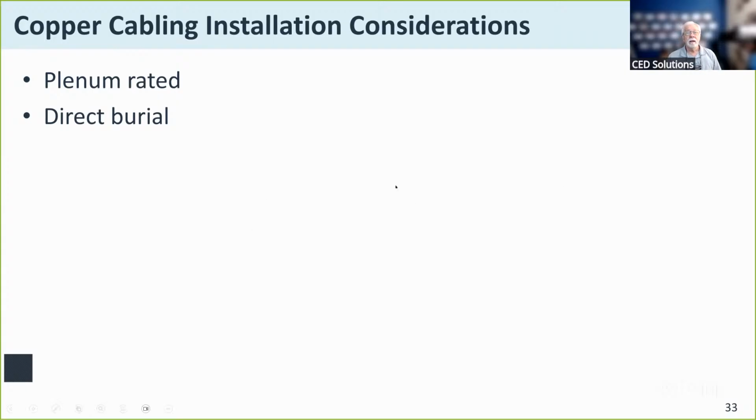There is one version of the twisted pair cabling that is referred to as plenum rated. Plenum rated meaning that it is okay to run it in pretty much close proximity to the air conditioning venting for the HVAC systems. The plenum cabling, that orange cabling that we looked at in the wiring closet, that's plenum rated cable. The ends are molded into the cable. It's not crimped on with openings. The PVC coating, it's very specialized. It doesn't burn. It will melt, but it doesn't burn and give off these noxious gases that can kill us.